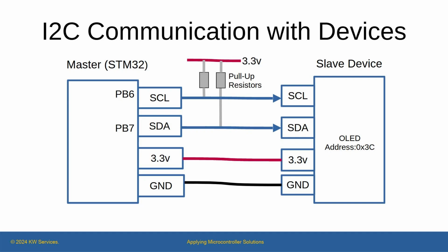Inter-Integrated Circuit, I2C, is an interface for communication between a master and one or more slave devices. I2C consists of two signals, SDA and SCL. Each device uses a specific address. The signal lines will not need pull-up resistors, as the OLED device includes these. Certainly, the MicroPython I2C driver handles the complexity of the I2C protocol, as we shall soon see.